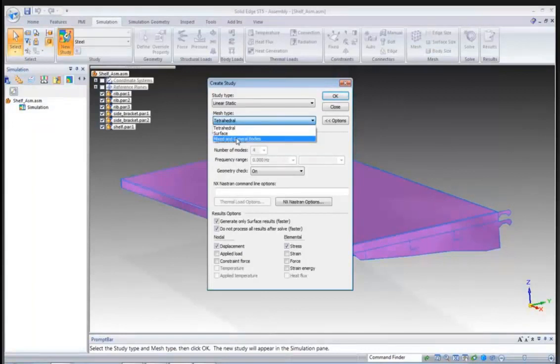So let's say you have a turbine, and you have the base in the middle of the turbine, which is a solid part, and you have the fins, the blades coming off, and those are surfaces. You can join those now with a unified body, even though that's really a surface coming into a solid part, which is a non-manifold body. We can do that now with ST5 simulation.